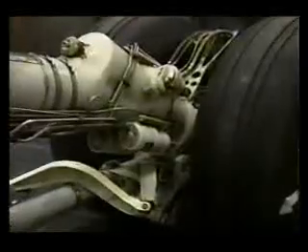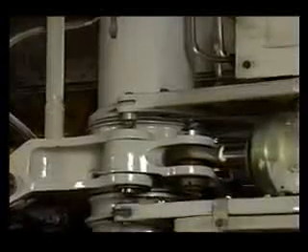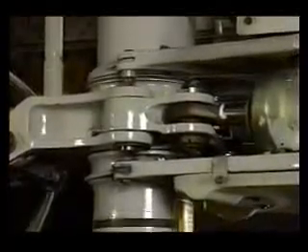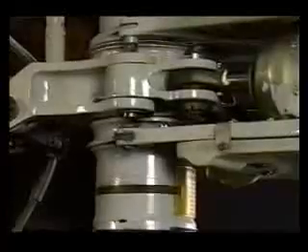There are many trouble spots in the wheel well and landing gear area which should be examined closely during inspections. All high-strength steel surfaces which are subject to corrosion fatigue, all exposed surfaces of struts, oleos, arms, and hardware, much of which is unpainted, exposed electrical equipment, axle interiors, and any crevices between stiffeners, ribs, and lower skin which trap water and other debris, magnesium wheels and bolts, where you may have dissimilar metal contact and exposed rigid tubing, especially under clamps and identification tape.